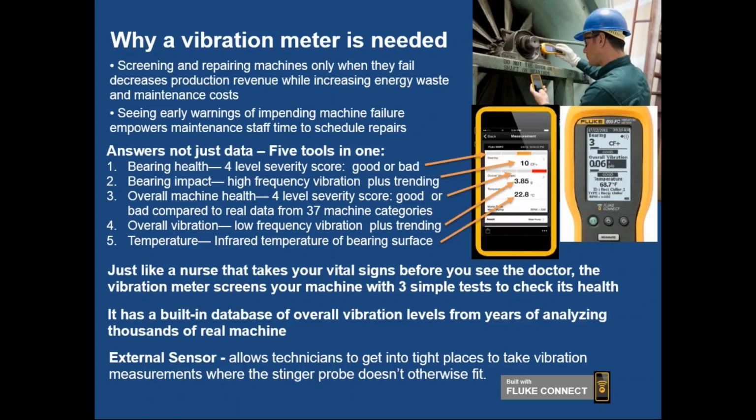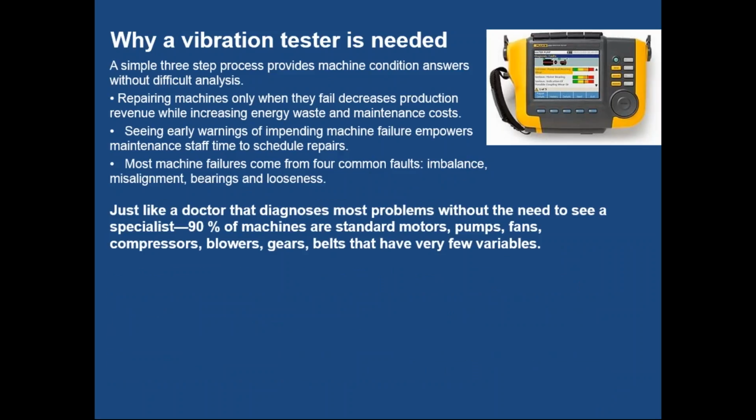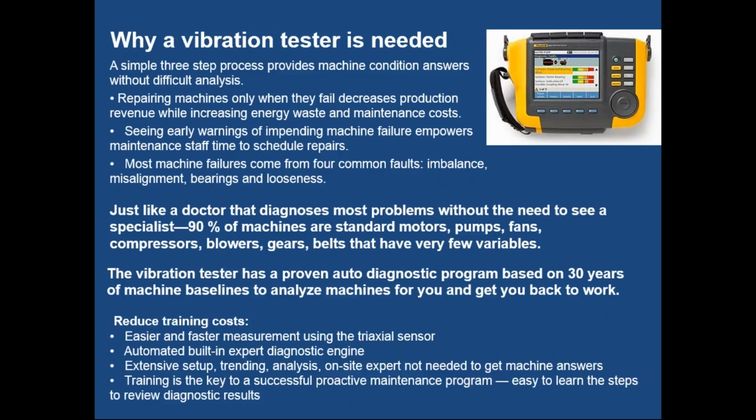And the vibration tester, what is it used for? Well, it's used for knowing what the fault is when a machine has a problem. Remember, there's 4 common faults: imbalance, misalignment, bearings, and looseness. And just like a doctor that diagnoses most problems, this is going to find 90% of the problems with standard machines that have very few variables. And the proven diagnostic program with 30 years of machine baselines is going to help you get your machines up and running.